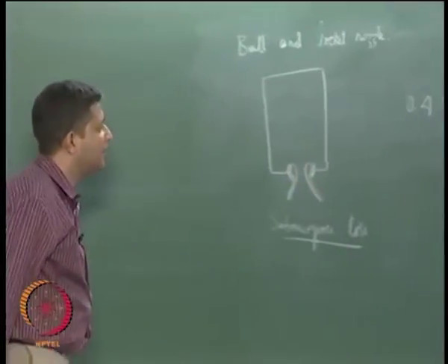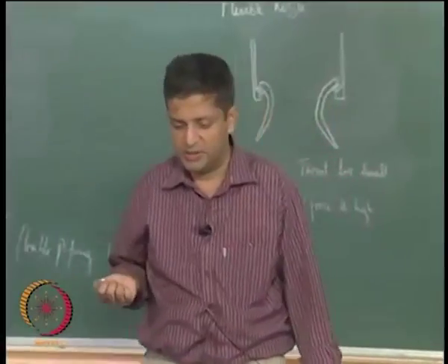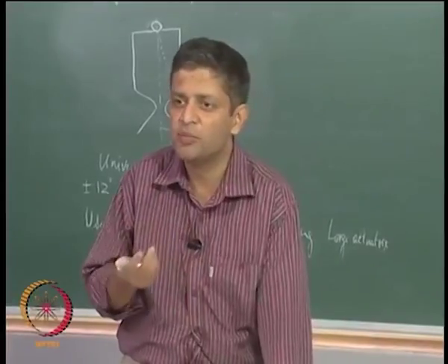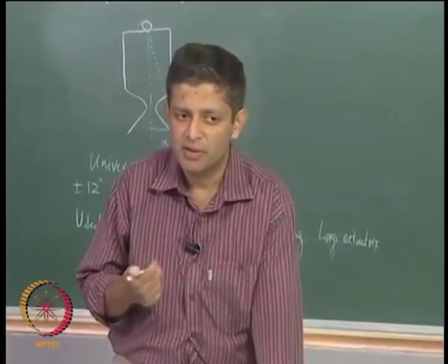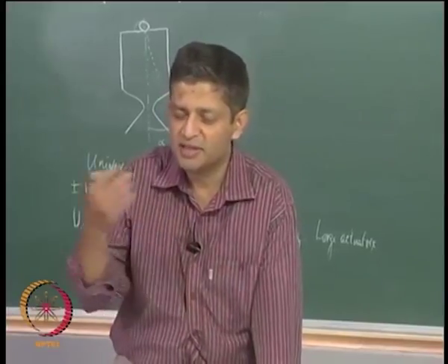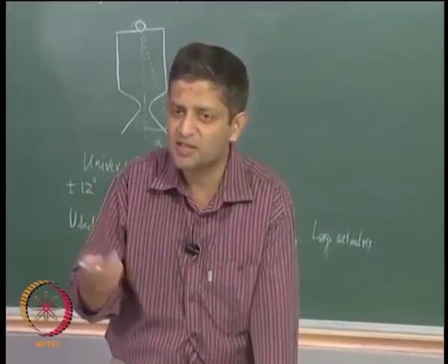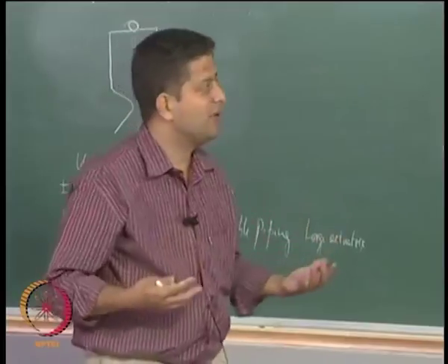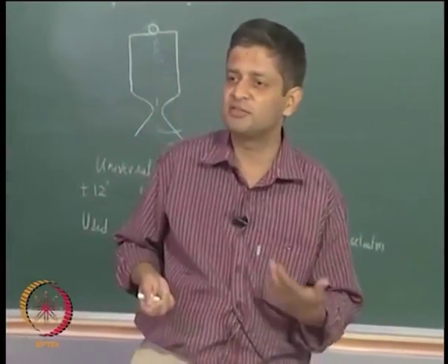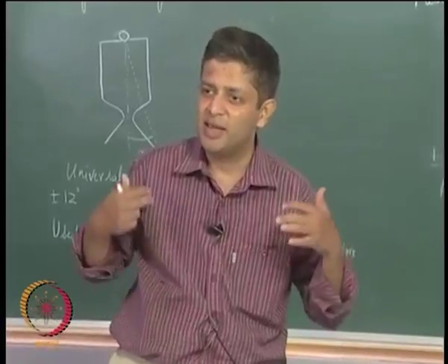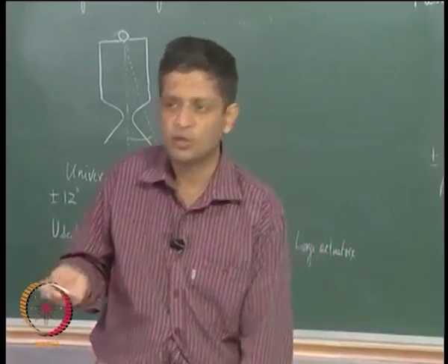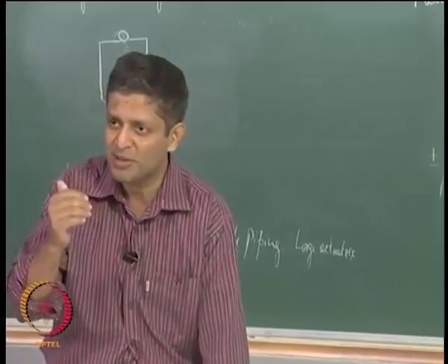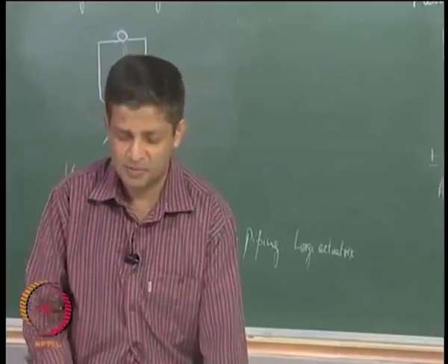ISP. And if you remember the discussions that we had in the morning, that is, if this propellant were aluminized propellant, then we discussed that the condensed particles do not expand and they cause loss, right. This gets coupled with that, and depending on the percentage of aluminum present in the propellant and the amount that the nozzle is submerged, the loss could be higher. I mean, it is within this range. It could be higher if it is more submerged, lesser if it is less submerged. Okay.